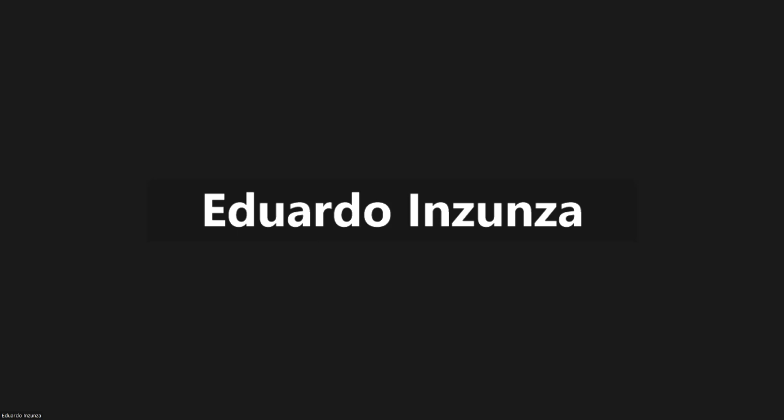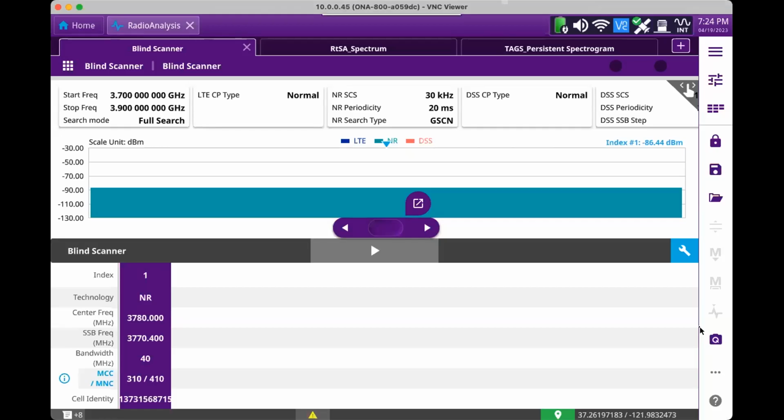So Eduardo, as you're tuning, I'll answer the question: what tools are we using to tune into the flexible time slot? The product we're discussing is the Viavi One Advisor 800, where we have GPS attached, and either a directional or omni antenna. We are able to demodulate, do some signal analysis, and get to the time slot allocation. We're using our tool, which is set up to automatically understand the frame structure. Hopefully that helps. Thank you, Dan.